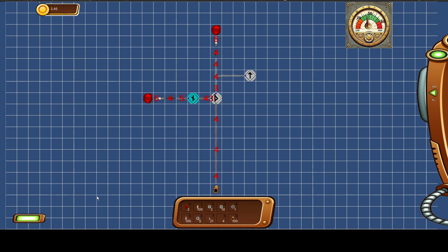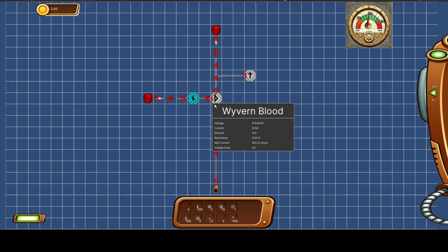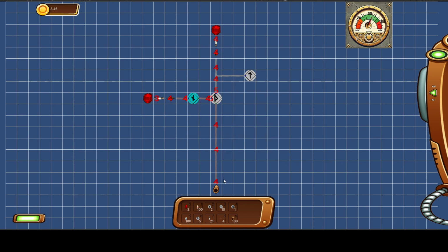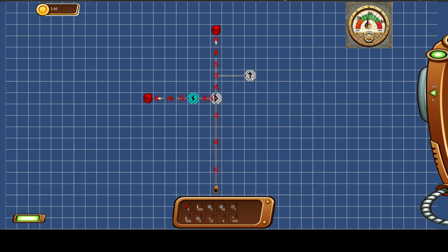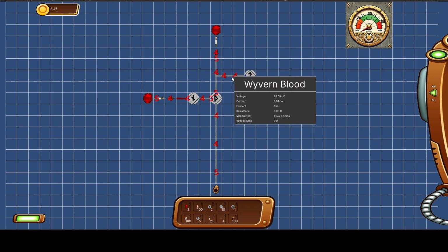So yeah, you can see here because power is going to this transistor, power is being shunted here to the ground. And you'll get very little going over here to this emitter. But if you switch it off here, pretty much all your stuff's going to be shunted over here to this emitter. Now there's not a lot of power going to it because this is a 1 kilo ohm resistor, so the overall current's pretty low.